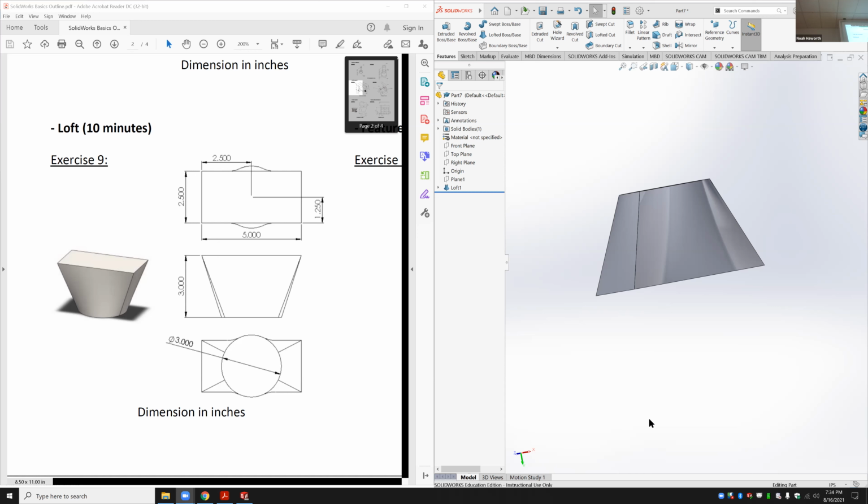You can just do escape. And click that line that you just made. Hold down control and then click the origin right there. This one. Yes, that. Now go ahead and exit sketch, and you should be good. That's probably right. There we go. It's not fully defined, but it's better than before. We'll go with that. Thank you.